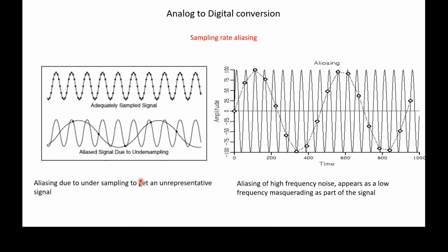This is why one would want to filter out frequencies in your signal that are higher than those that actually make up the signal you're trying to measure. Noise often has high frequencies in it. This is why you'd want to get rid of them. Because if you sampled those, you would find out, I have a very low frequency in my signal, which should not be there.